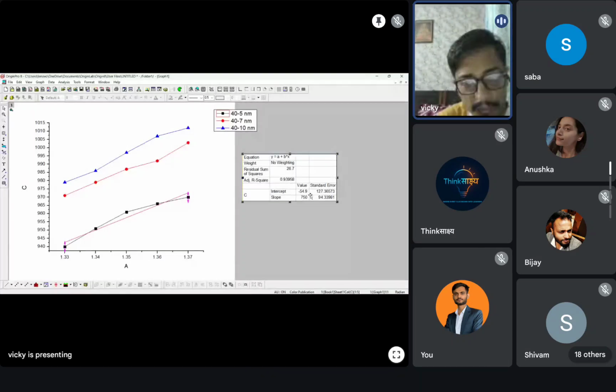Right? Similarly, you can do the curve fitting for the data in column B and column C also. So in this way, you can do the linear fitting. And if you want some other kind of fitting, cubic spline and some other options are also there. If you go again to the analysis part, the fitting part, you can fit a polynomial, and we have some different options. A dialog box opens. You can select how many data points you want to apply it to, and what kind of graph you want. So you can do all these things.